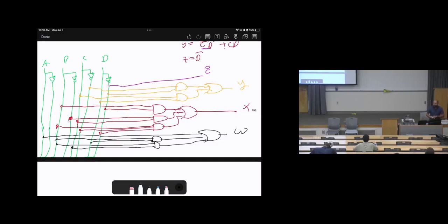Okay. Now again, in hardware, maybe I don't have AND and OR. Maybe I have NAND implementation or NOR. And you know, of course, how to convert this to NAND implementation or NOR implementation. So it's depending on the question. If the question didn't mention anything, then that's enough. If the question says convert this to NAND implementation, then keep this in mind. If you need to convert this to NAND implementation, put bubble here, bubble here, bubble here, bubble here. Here are bubbles. Then keep in mind to put an inverter here.